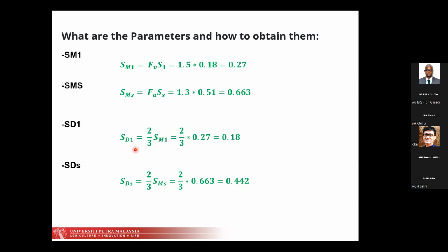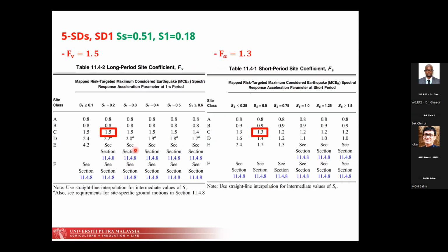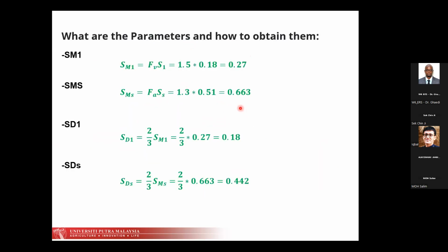But if we talk about ASCE 7-16, we only provide S1 and SS, and it will do this calculation automatically, and we provide it with the site class also. But it's important to do this manually because it's related to the other steps. So I believe that every engineer, when they have a specific structure, should compute them manually before going to software.